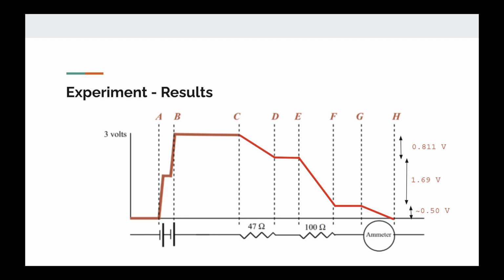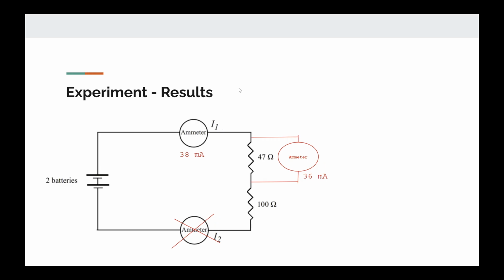The experimental results can be continued as such by creating a diagram of the drop in voltage. You can see that it drops to 0, and it drops based off of the resistance applied. The ammeter will have some voltage drop because there is some resistance in the measuring circuit behind the meter. Continuing with the lab, some other results.